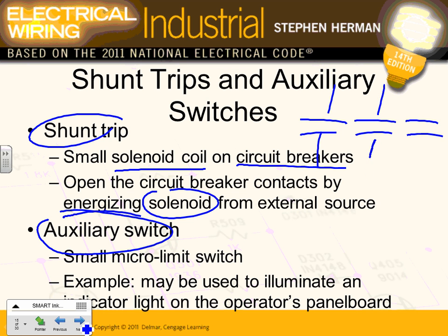Auxiliary contacts: the circuit breaker, guys, at least comes three-phase, comes with three contacts, right? These are three-pole circuit breakers. Then most of them come with auxiliary contacts on the side, normally closed or normally open, that you can wire to do certain things. So if you want, every time the circuit breaker is on, you want a light or a message to come to your iPhone, you have an auxiliary contact, interface it with a communication device, and every time your air handling unit is running, it gets you a message in your iPhone. That's how important the auxiliary contacts are.